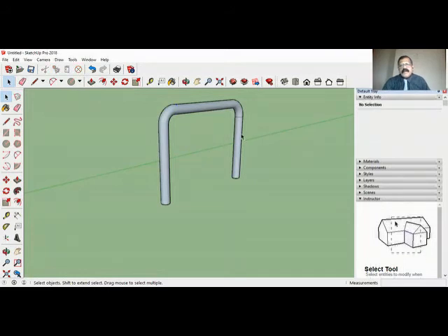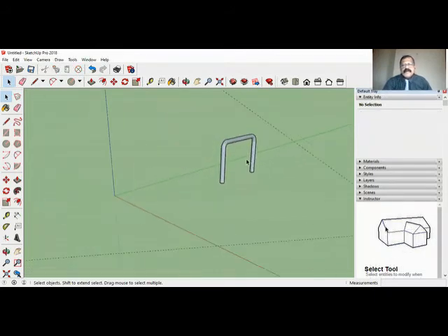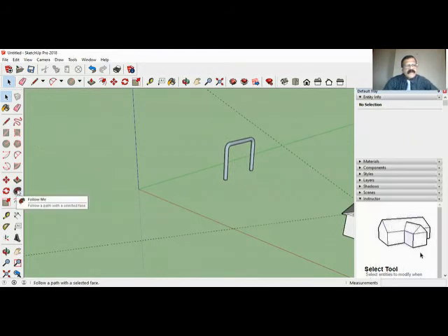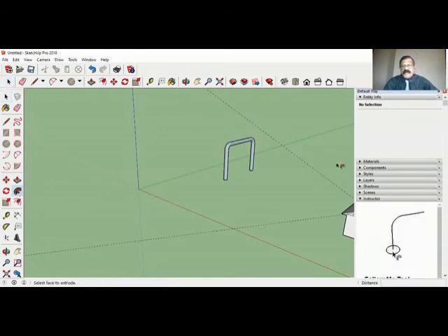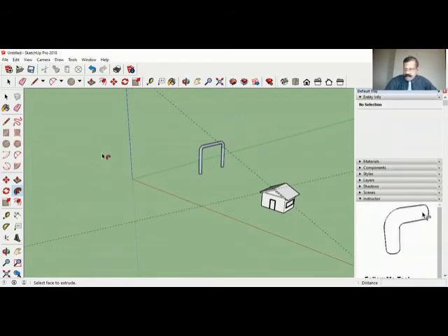Same way, cross window, select this, press shift to deselect, make it soft, it has gone. So the follow me is a very interesting feature. You can see how it does follow me. Okay, this is follow me. I hope you got some idea.